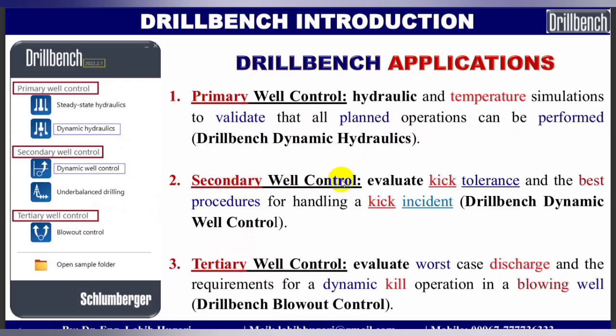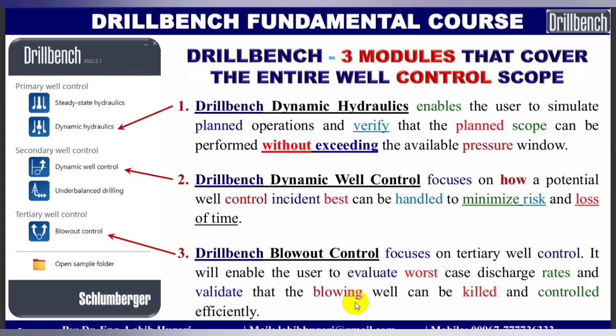Secondary well control: evaluate kick tolerance and the best procedure for handling a kick, Drillbench dynamic well control. Tertiary well control: evaluate worst case discharge and the requirements for a dynamic kill operation in a blowing well, Drillbench blowout control.